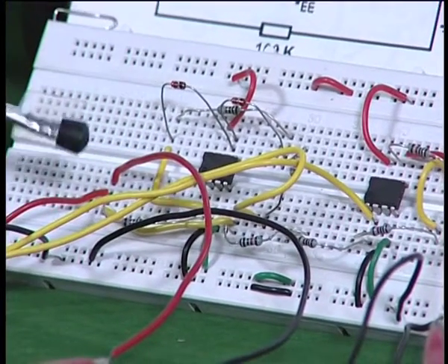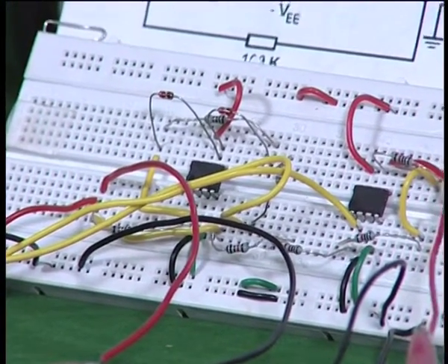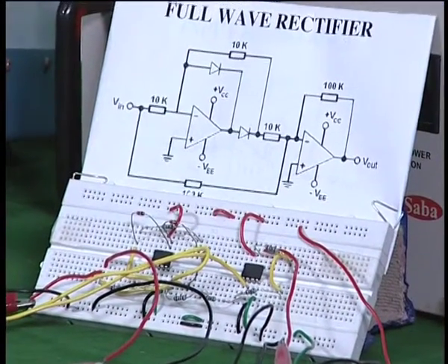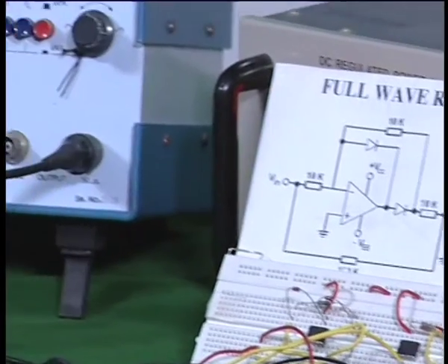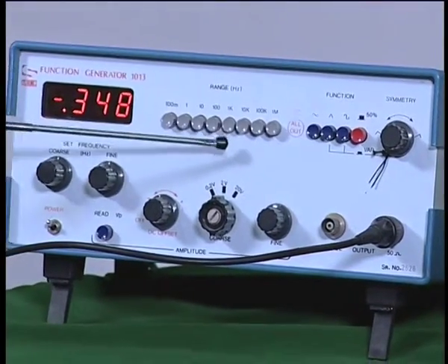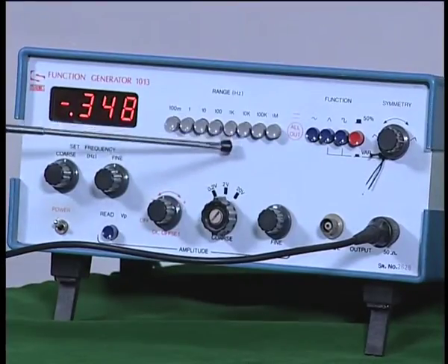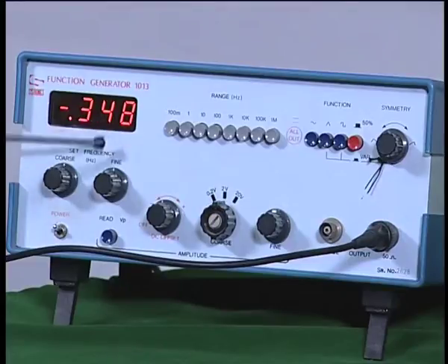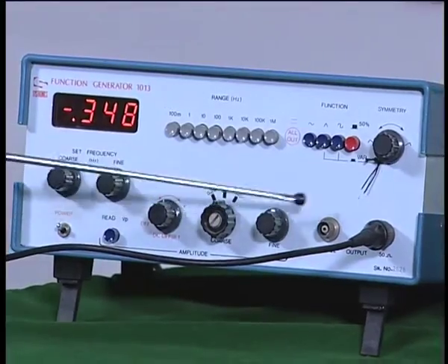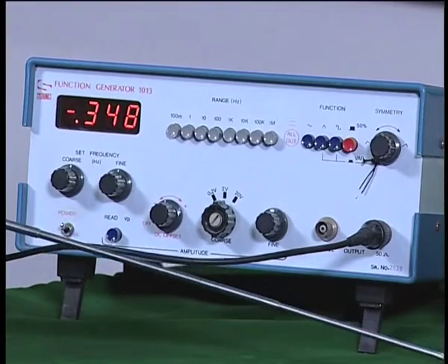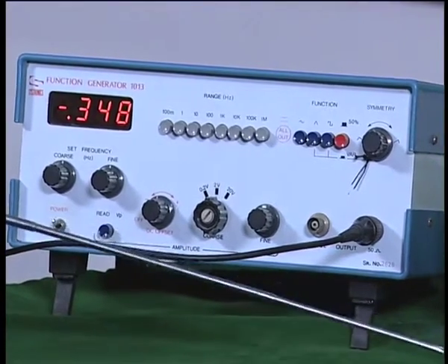So, the circuit is exactly the same as what you see here, and I have now given the input from a function generator as before. You have the sine wave input and the frequency is around 1 kilohertz, and therefore, I can measure the frequency and the amplitude over here, and now this input is given as the input for the circuit.